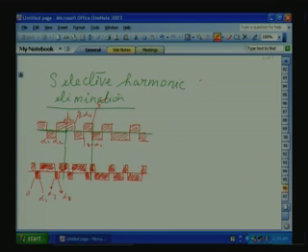So, let us do the Fourier series for a general PWM with a general notch. The harmonic analysis, if you see the Fourier series, that is Vn. Vn can be written as 2 into VDC, our DC link voltage, divided by n pi.